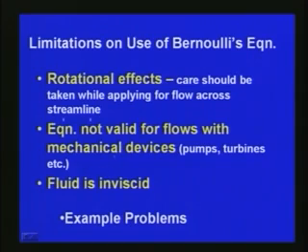And as we have already seen, one of the important assumptions in the derivation of Bernoulli's equation is that the fluid is inviscid. Whenever viscous fluids are considered, Bernoulli's equation can still be applied, but it is one of the limitations, because it is not 100% correct for viscous fluid; the equation is derived based on the assumption that the fluid is inviscid. So, these are some of the important limitations on the use of Bernoulli's equation.